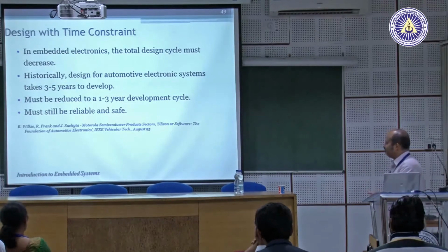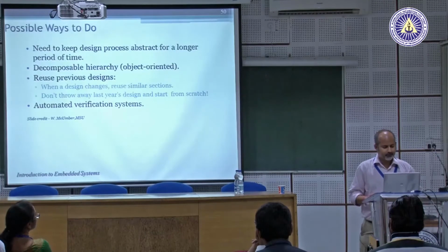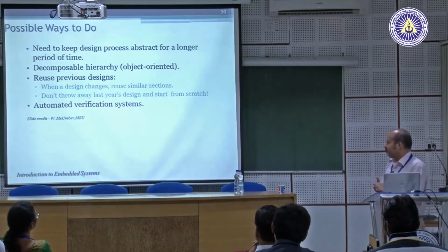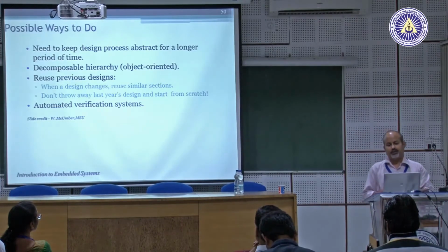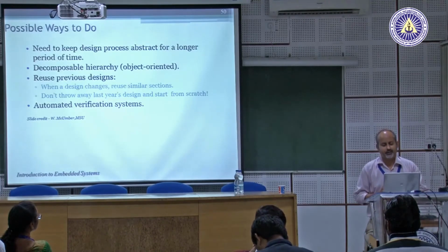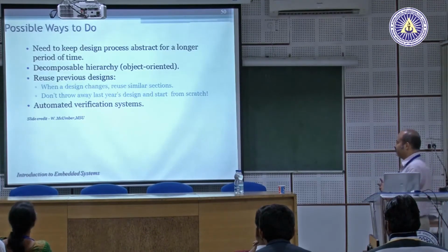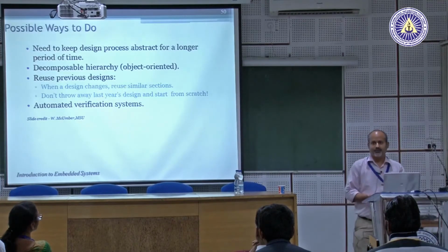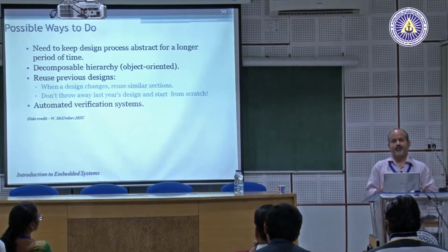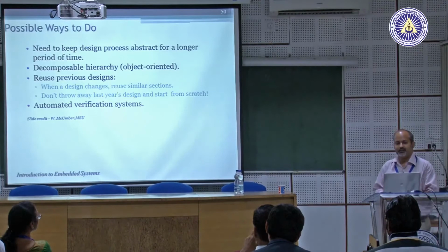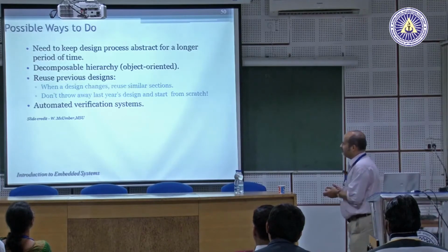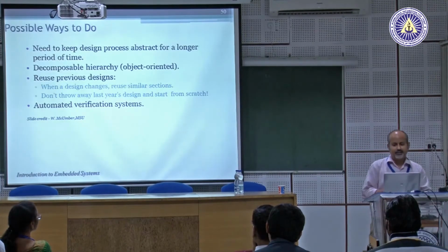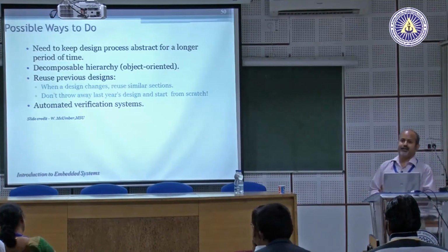So this is talking about development cycles, so we'll not worry too much about that. One approach that people are advocating nowadays is to do something very abstract, right? And this comes mostly from Europe. The American way was what we were discussing before, right? You choose the processor based on the market and other constraints, you build the board, then you build the software, and then it usually works because it was simple. Now, because of this large complexity, you have to start at a higher abstraction level and design in abstraction as much as possible.